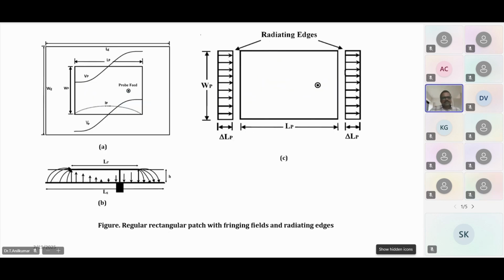So the basic operation of a microstrip antenna is like this. Whenever two metallic layers are there, a rectangular cavity is formed between the patch and the ground plane. In the substrate, standing waves are generated whenever the feed is matched with the patch load.